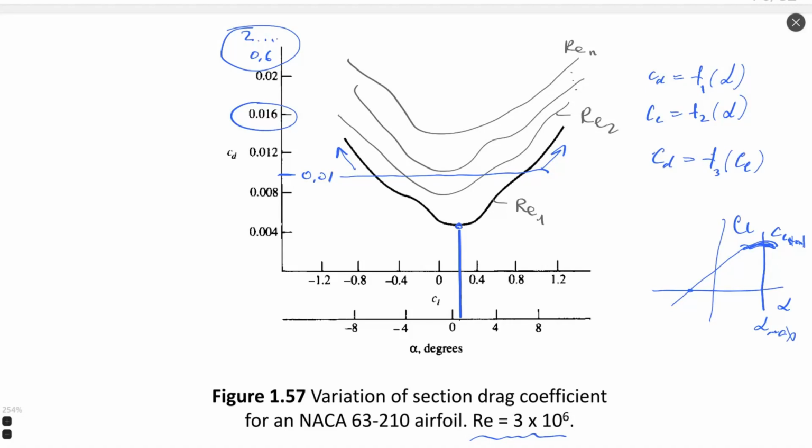So the curves will be different, and a lot different, not just 1%, 5%, because drag is formed mostly by skin friction. Drag is highly a function of skin friction. This is why skin friction is strictly related to Reynolds number, because it uses the same viscosity definition inside the skin friction and inside Reynolds. It has viscosity.